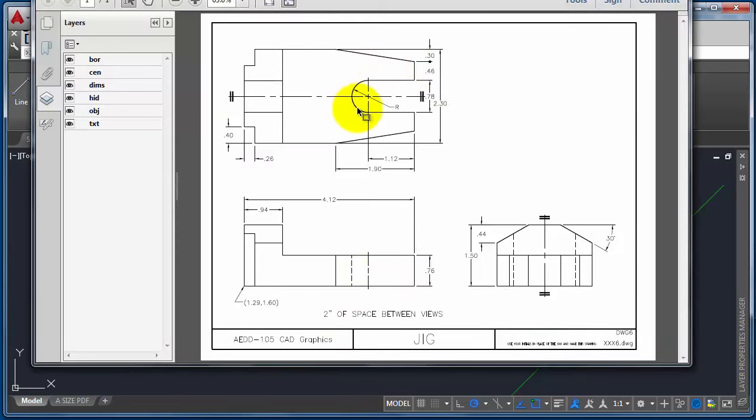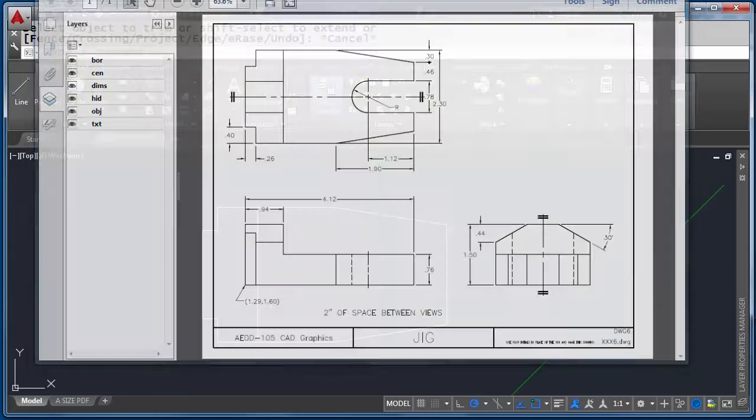The next thing I need to create in that top view is this notch. I see that this has a regular radius with the radius symbol, but the radius itself is missing. The information about the shape actually comes from this linear dimension, which isn't the radius, of course, but actually the diameter. I also know the position of the center of this feature from this linear dimension.